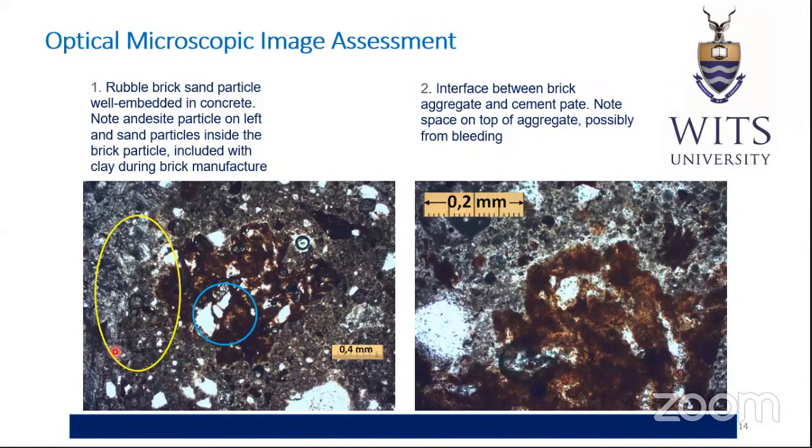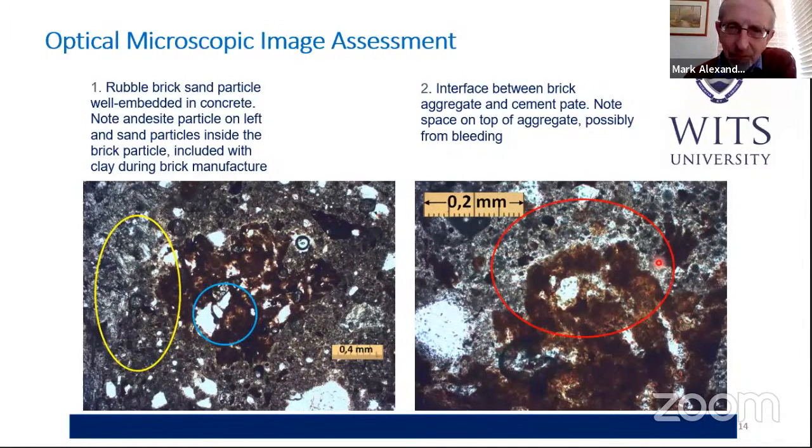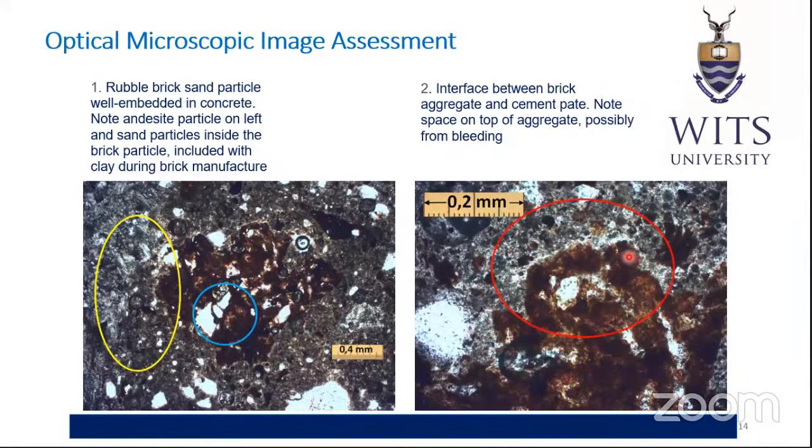And this part circled in yellow is the andesite particle. Coming to the right-hand side image, this part here circled in red is the line between the brick and the cement paste. It's the interface that shows a perfect bond between the brick particle and the cement paste, which also shows...